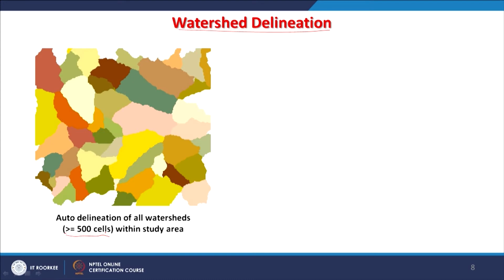One problem I mentioned earlier in the previous lecture, which I am going to repeat, is that while doing this you will have problems or limitations of surface hydrologic modeling along the boundary or margins of your input digital elevation model, which you can see. Because remember, one watershed ends, another starts.